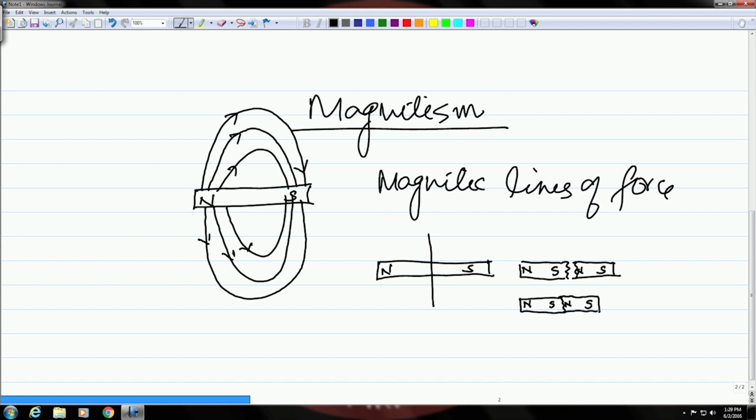Similarly, if you have a crack on a magnetized surface, let us say this surface is magnetized and you have a crack somewhere, then along this fracture the magnet which is created is going to remain, and it will have its own field also. In a similar manner, if you have a discontinuity or a crack, this will also create a tiny magnet around it, like what you saw in this case.